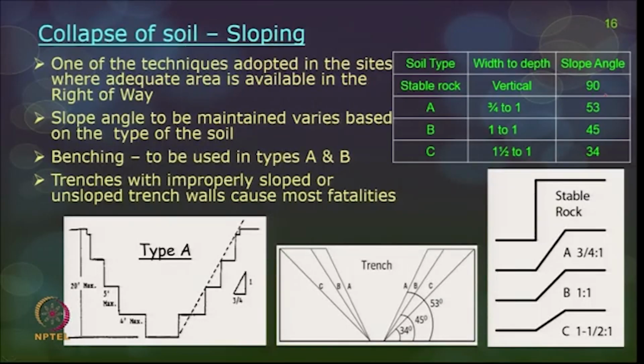Instead of cutting the earth vertically, you have a slope, so that your cut earth naturally will not yield and cave-in does not happen. For stable rock which can stand on its vertical line itself, you need not think of a protective measure at all, or even an angle.